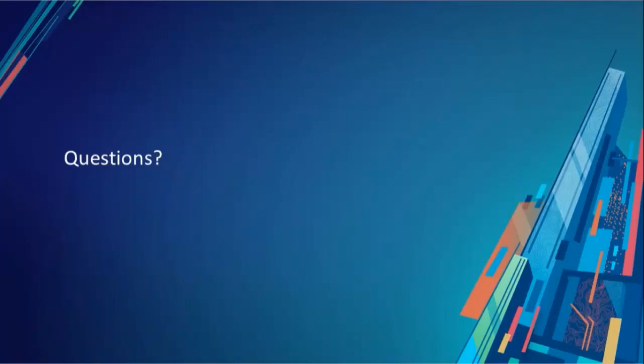Actually, I think it is. We can process the RCS file on SiteScan and send it to BIM 360, where you can connect with AutoCAD Civil 3D. But I'm not sure if you get the surface model. You can get the point cloud directly, but I'm not sure about the surface model. Maybe they pull in the DEM file and import that as a surface. Yeah, that's possible.